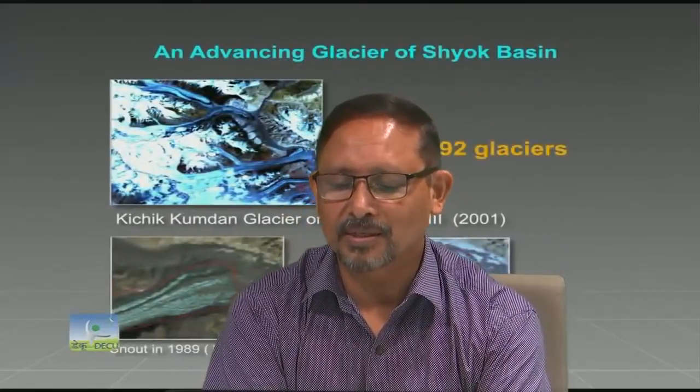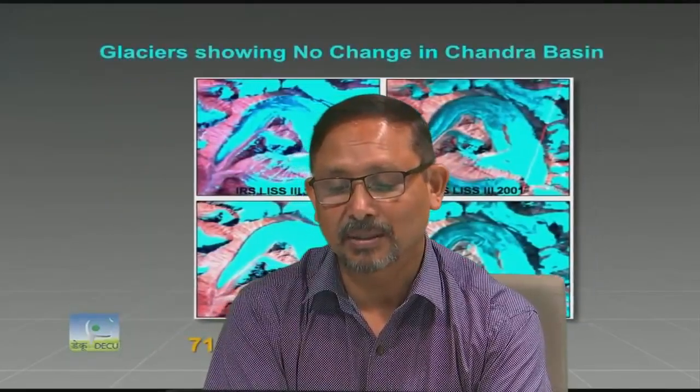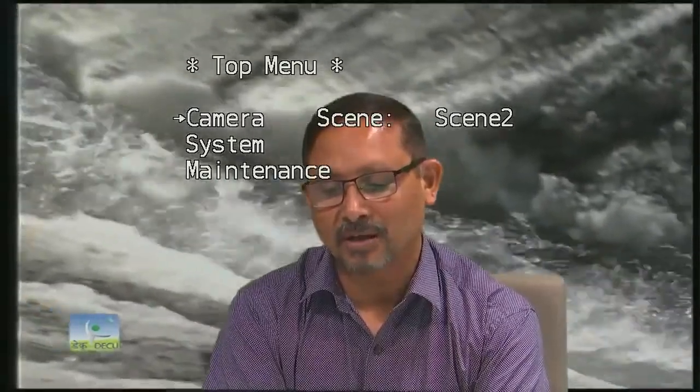Terrain analysis is useful for reducing forest fire. Actually, you know forest fires happen in the ridge area where the dry zones are. In the terrain wetness index, the wetness value is very low there. There is no wetness; it is a dry area. So dry areas you can find out with terrain analysis, and if forests are lying in that area, then there are more chances of forest fire.